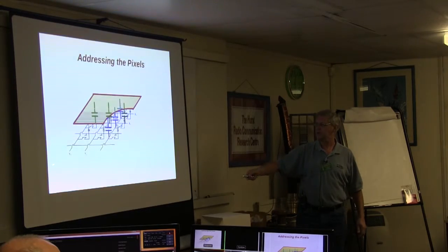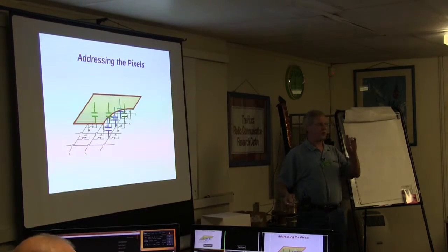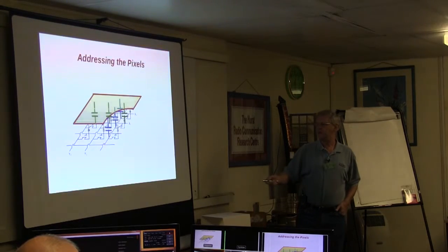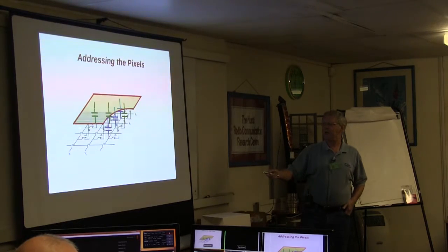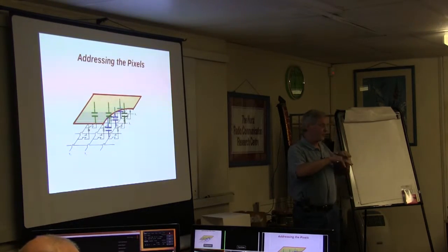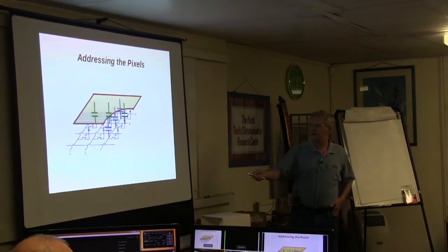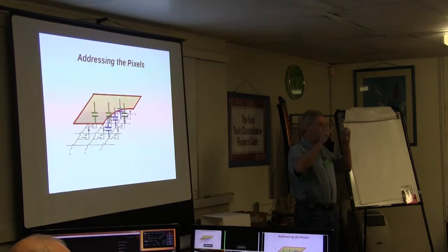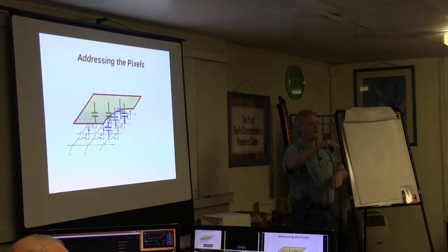the vertical rows, which carry the actual signal needed to manipulate the pixel, we could put a voltage on the Y signal there, and it would go through the source and out to the drain, and it'd be applied across this liquid crystal. The liquid crystal, by the way, has got some capacitance on it. So once we've applied that voltage, we can turn off the transistor and the voltage will remain across the liquid crystal, purely due to the capacitance on it.